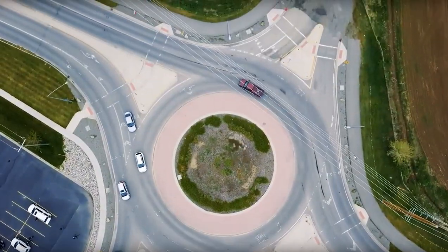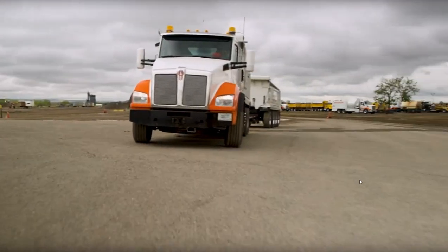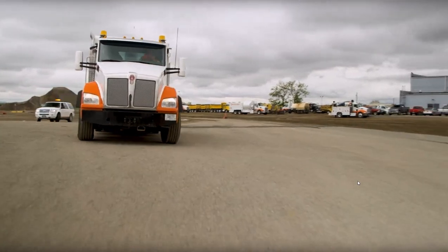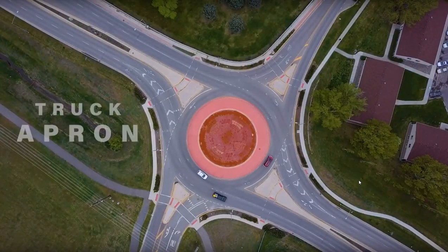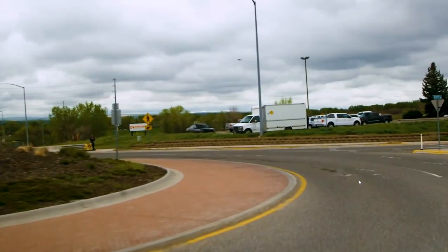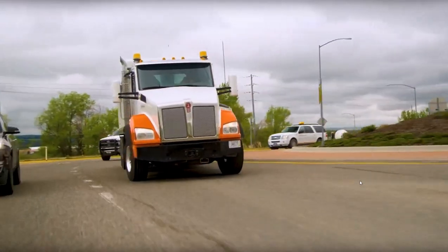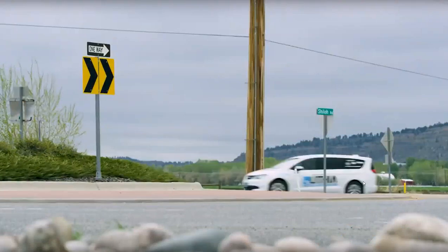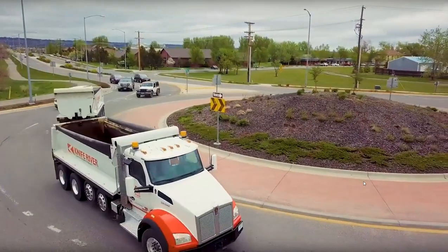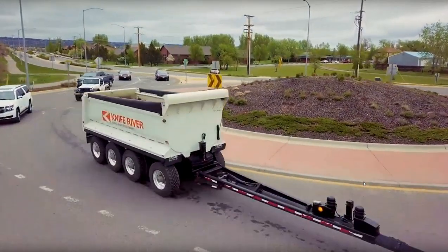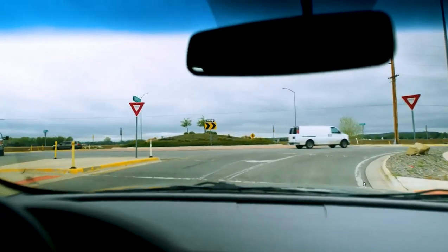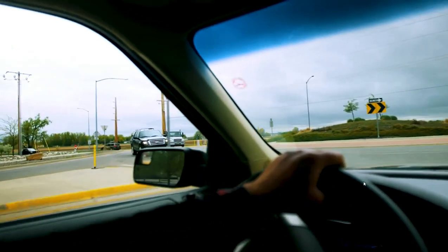Yes, we thought of that. Montana's roundabouts are designed for big rigs. They have what's called a truck apron. There you go. Look at that truck apron. At the center, the trucks and larger farm equipment are allowed to drive on going through a roundabout. Cars shouldn't drive on it, but it's designed for your rig's off-track. There you go. And even that huge long trailer didn't off-track very much, right?